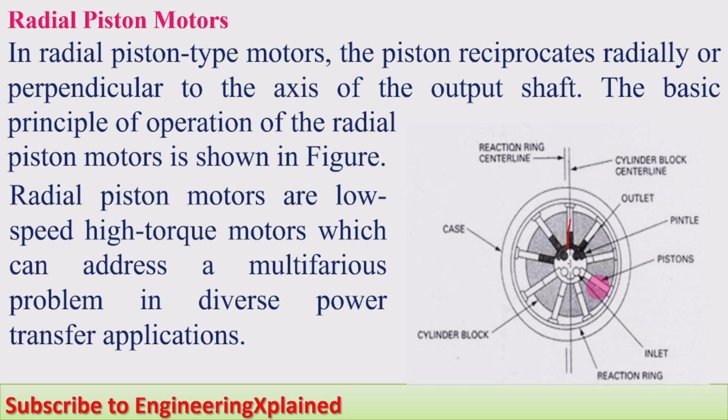You can see here the pistons reciprocating inside, and fluid enters here, and due to its force it rotates the inside rotor, and thereby the pistons reciprocate. And here also there is an eccentricity between the outside casing and the inside rotor. Here is the cylinder block center line as well as the outside reaction ring.